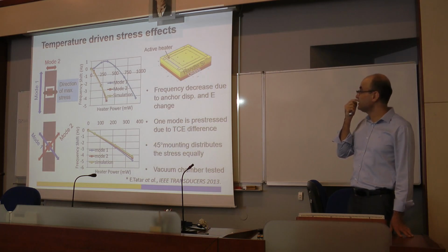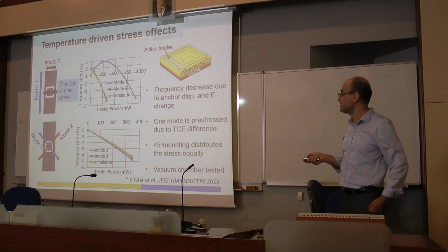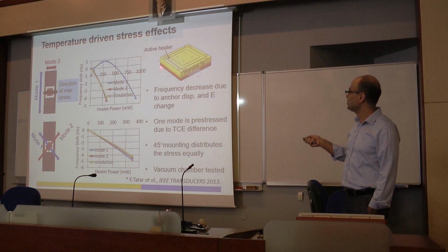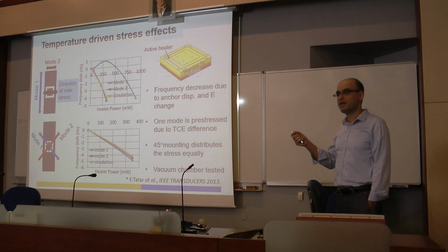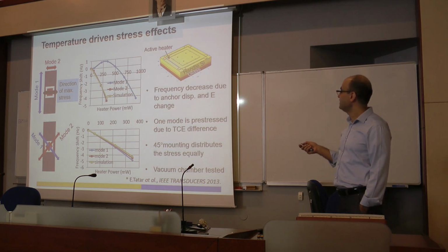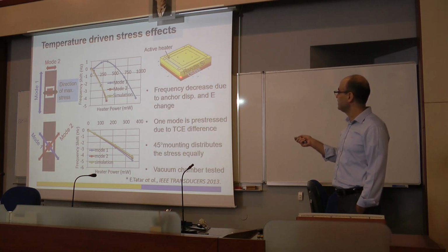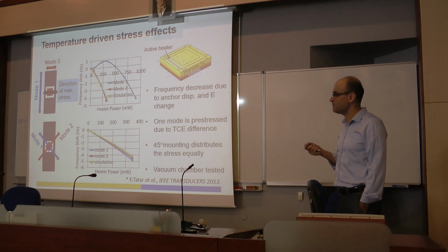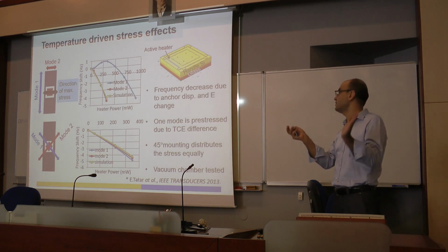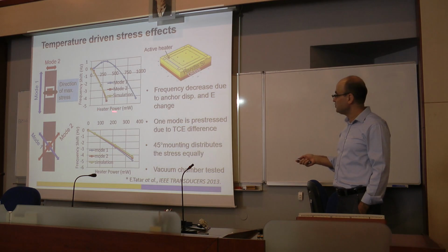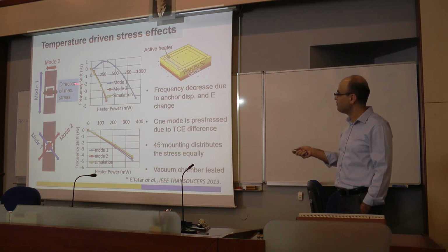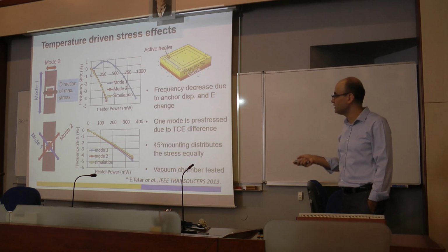So this is one of my first stress study results. I have a chip and I have a heater. When I apply heat, that will induce some stress on the device because this thing is fixed from the bottom. What happens is when you apply stress, it will open up like a flower. And when I sweep the heater power, when I make it hotter and hotter, mode 1 is vibrating in one direction, mode 2 is vibrating in the other direction. So I see a discrepancy between mode 1 and mode 2.